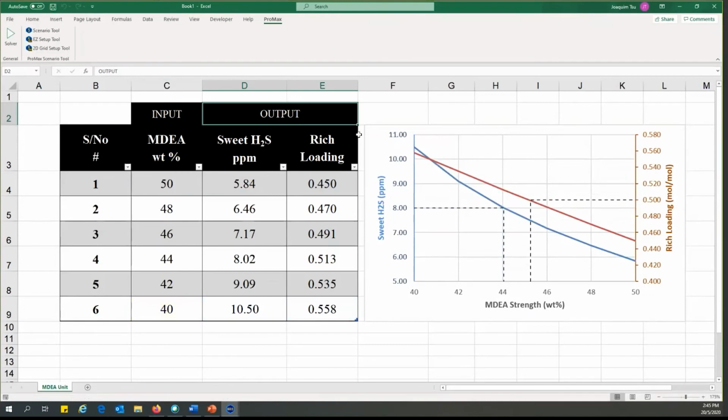So their historian will generate the plant data in an Excel format, and we can format this to run through all the plant data and then tell you how far off ideality, or how far off a clean system, you are. Doing it this way allows you to really plot control charts and have them have meaning, because you can compare the values with what it should be if you had a clean system. Okay, so in this case, scenario 2 is complete.